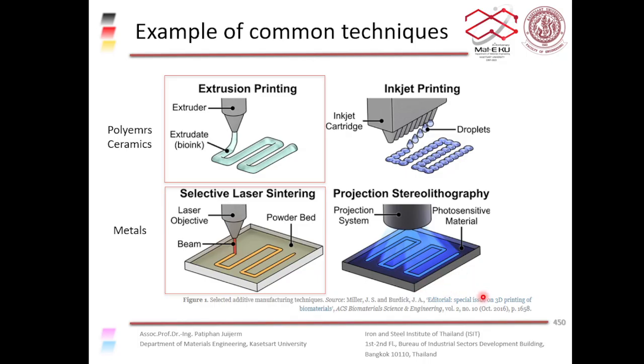So basically, you have a mask as the circuit of the chip that you want, and you have a photosensitive layer on top of your silicon chip. You shine light through the mask onto this photosensitive layer. The area where the mask is covering the surface, the photosensitive layer won't be developed, and you can just wash it off. The area where the photosensitive material is exposed to the light will harden. So you get this shape.